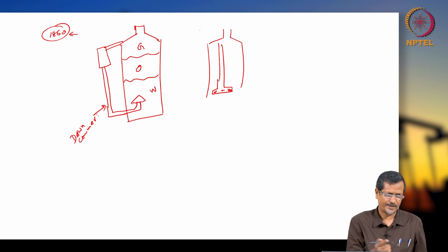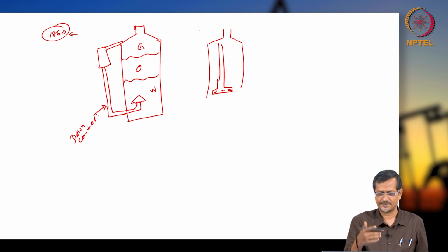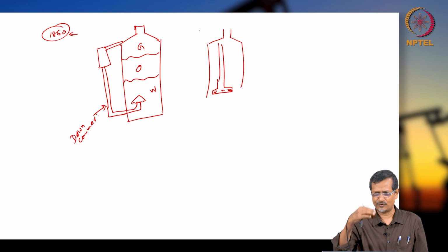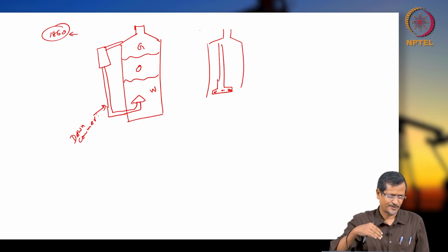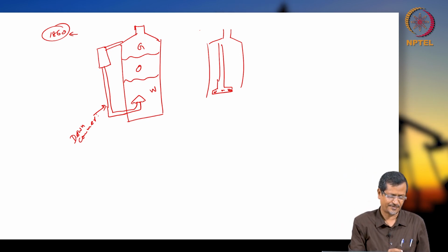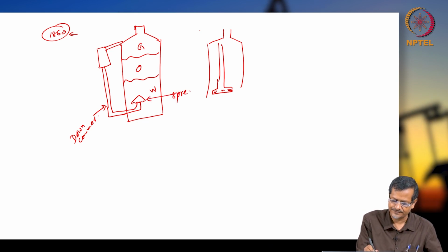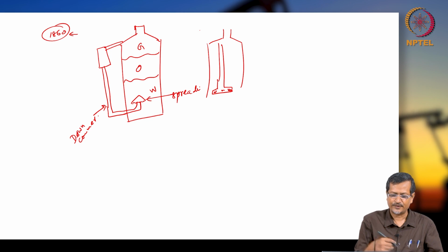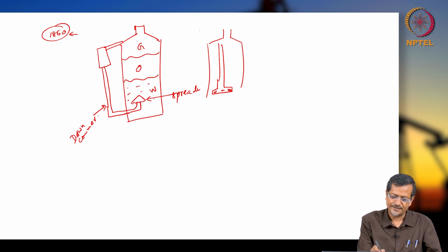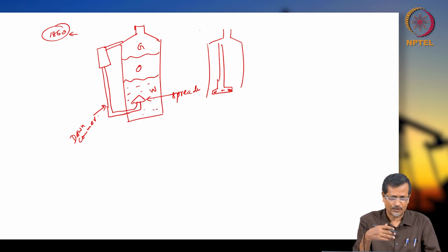So, the company will explain, but the basic arrangement will be like this: 3-phase gas, oil, water. It will not be like this: water on top, gas at the bottom, okay, because of density difference. So, downcomer is there, this is the spreader actually, okay, and you are giving this fluid in the water zone. So that water washing is possible.